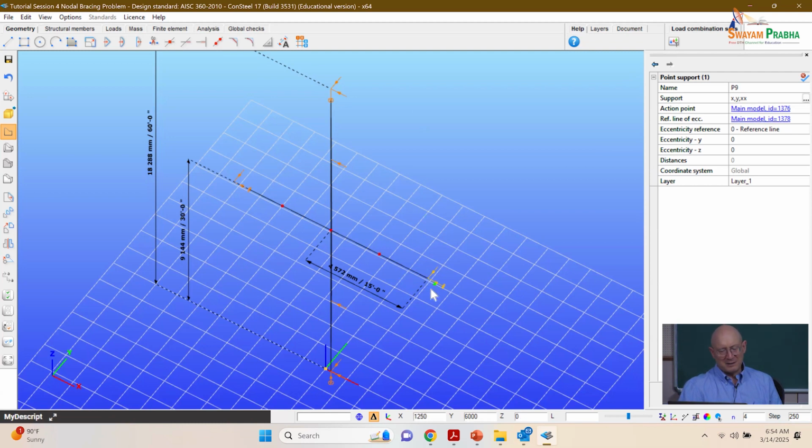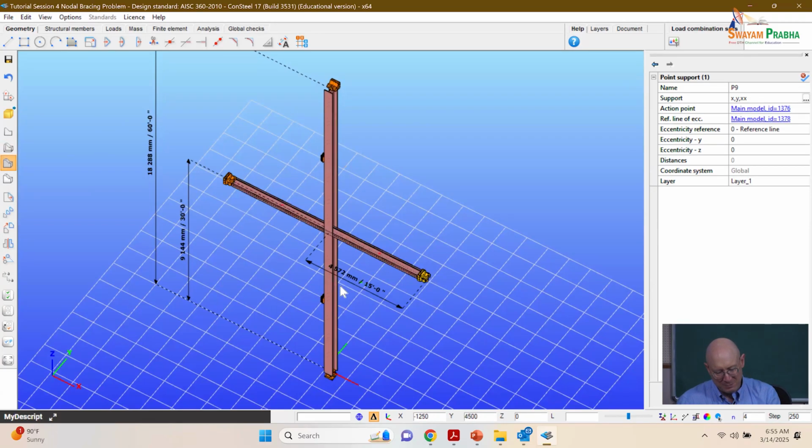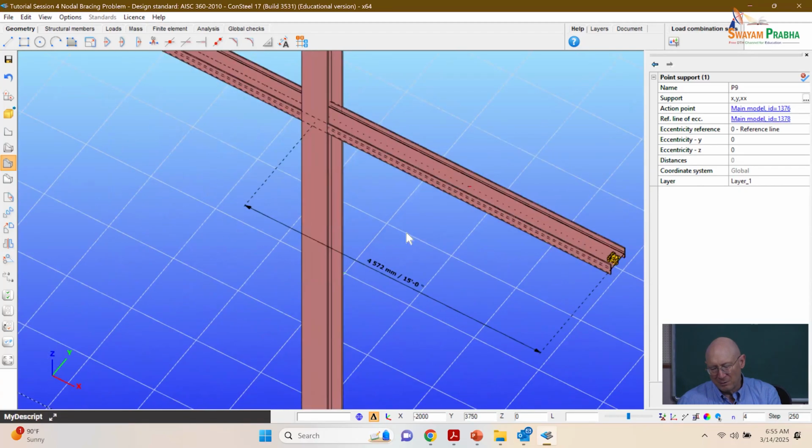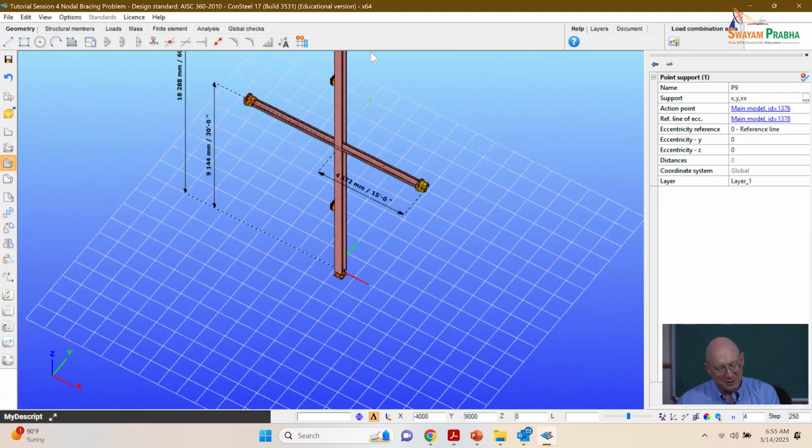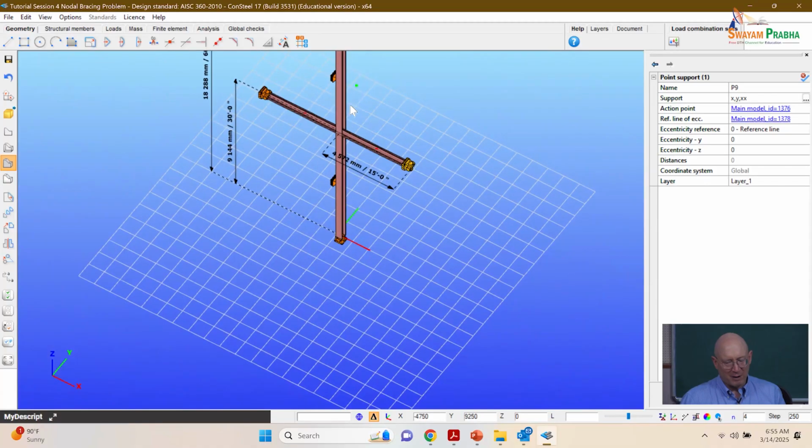The reason for that is if I restrain the Z, I would get something where when the column shortens, I would get some weak axis bending in this flying beam. And so we're looking to do an idealization where we're not producing bending in that beam. So here again, the beam is in strong axis bending in terms of supporting the column, buckling in major axis bending in the direction normal to this side of our shaft.